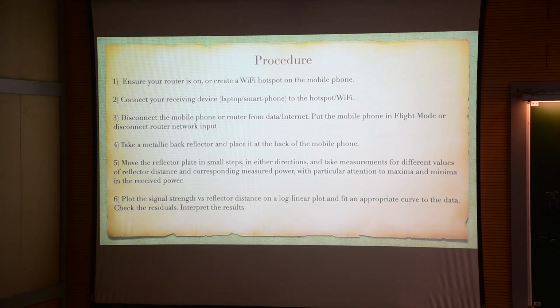Okay, and then we have to make sure where the physical position of the antenna is in your cell phone as well as in your laptop, so that it will be easy for us to measure the distance between the receiver and transmitter. So basically we are not measuring where the mobile is kept. We have to measure from antenna to antenna. So that will be your distance, and the antenna to the reflector. Okay, so those are the things we need to know, and I have explained a few of them.